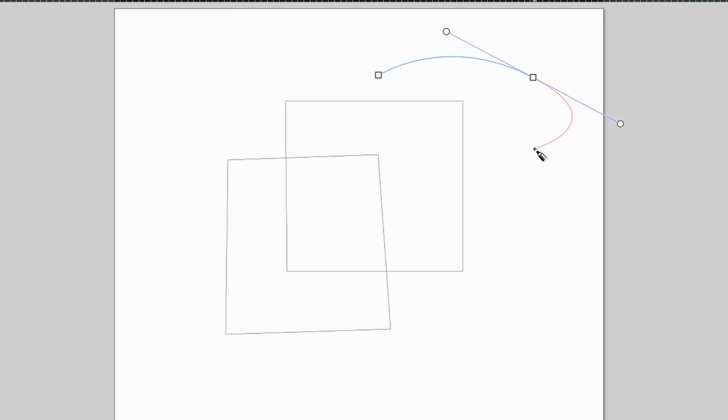You can get around this by simply pressing the right click. Right clicking will finish where you are, but it will not finalize the path. It will still leave it as an open path. The difference between an open and a closed path is the open path has 2 end nodes. A closed path is like these squares here. There are no end nodes, they all link up together. So the start point and the end point is this corner here, and it was the same on this one. However, this one is already open.